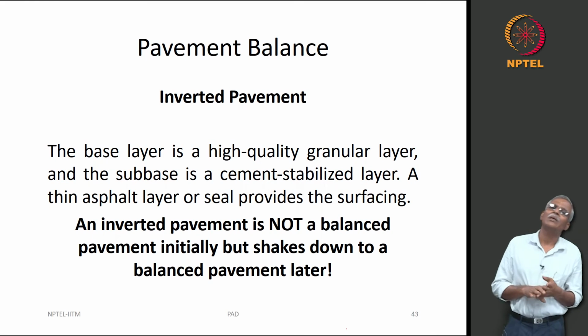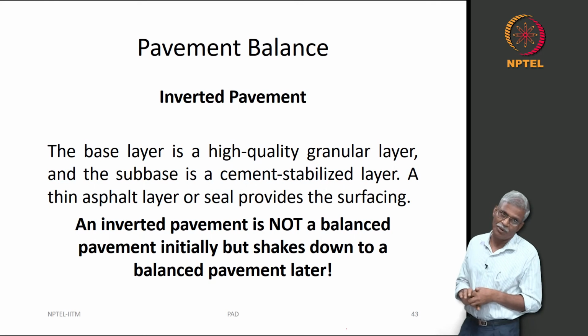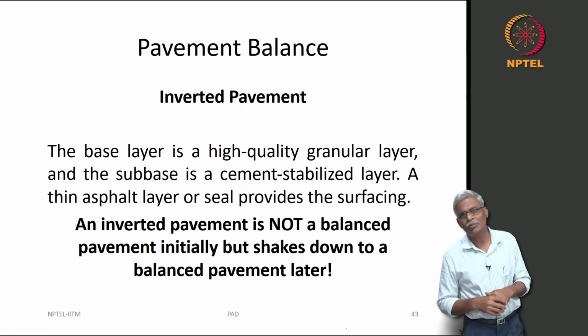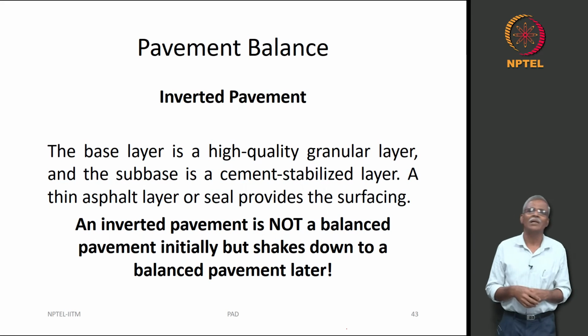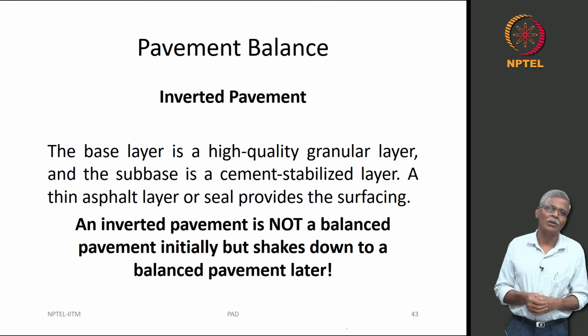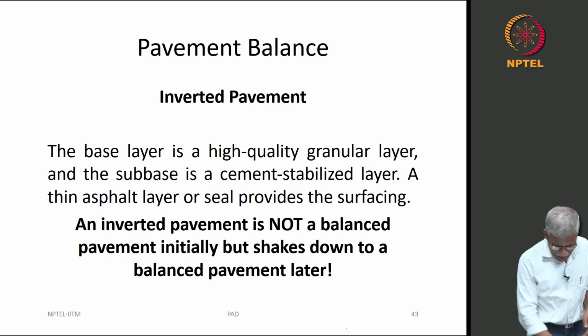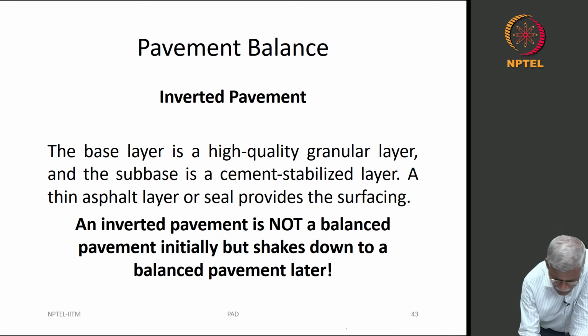The interesting part is related to the inverted pavement. Now, what exactly is this inverted pavement? In an inverted pavement, you can have a base layer which is a high quality granular layer, but your subbase could be a cement stabilized layer. So, let us take a look at it.